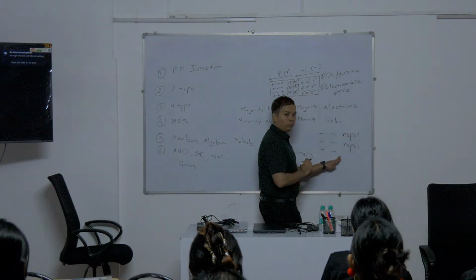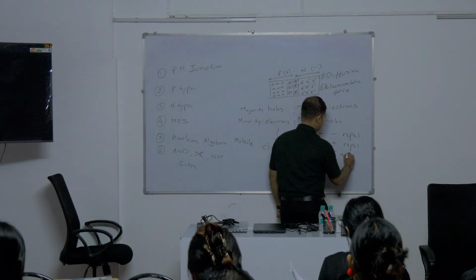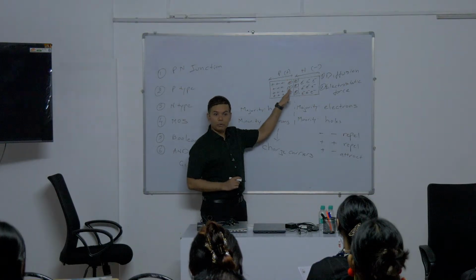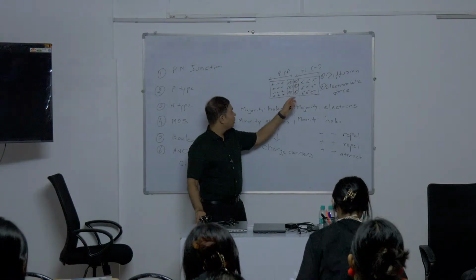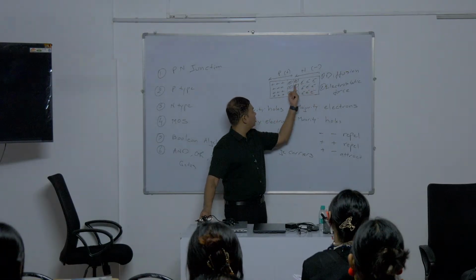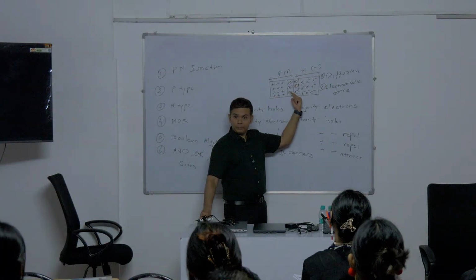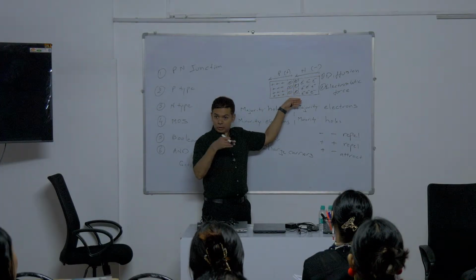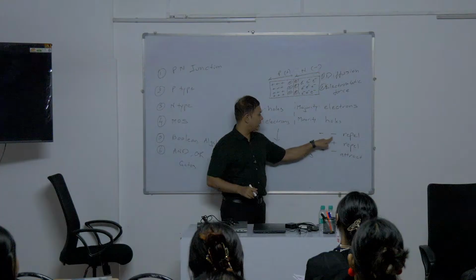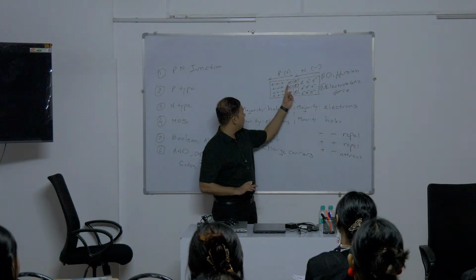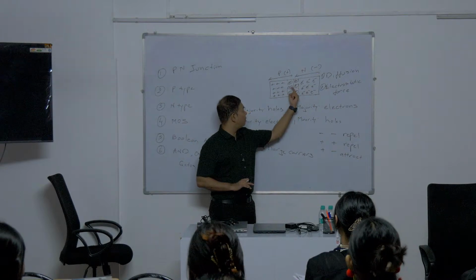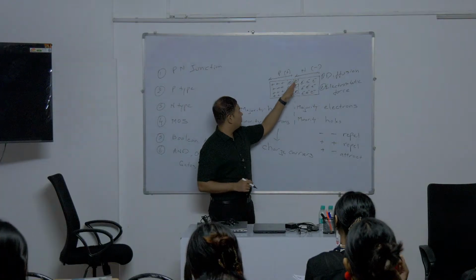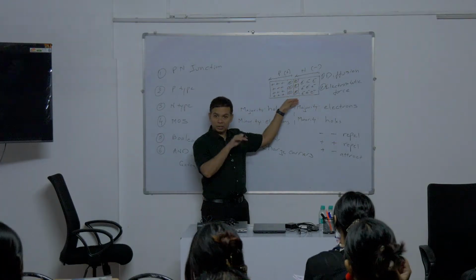And when we have positive and negative, it will attract. So just think about it: when there is a negative charge accumulated in this region, do you think that any more electrons will be able to flow through this region? Because this negative charge is going to push the electrons, because it is going to repel. That is negative and negative, yes or no? So this negative is not going to allow these electrons to pass in this region. Similarly, if you think hypothetically, this positive charge will not allow any holes to flow in this direction.